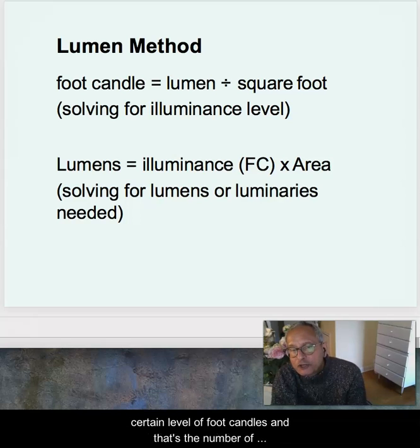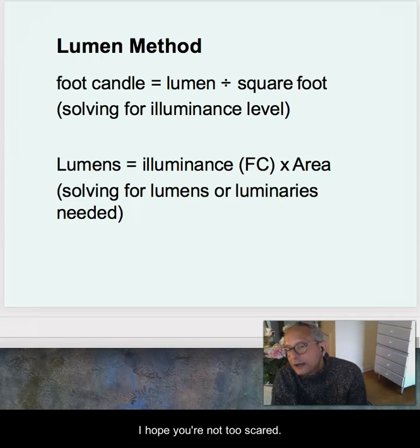And basically we want to achieve a certain level of foot candles, and that's the number of lumens that are generated divided by the square feet. So all there really is, it's really addition, multiplication, division. I hope you're not too scared. It'll be okay.